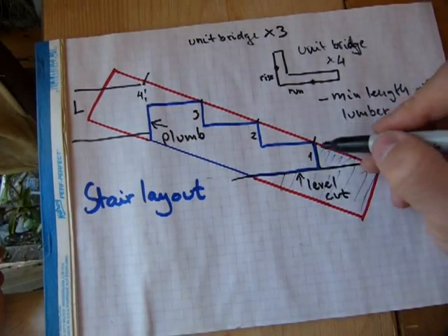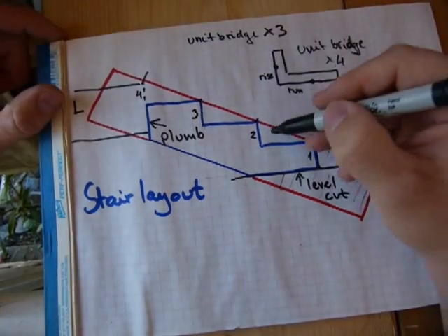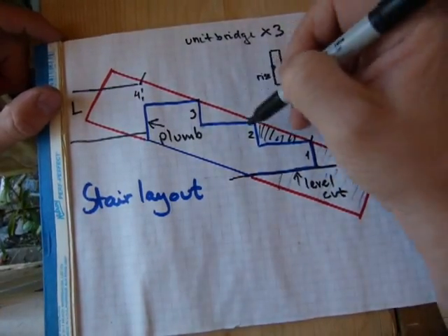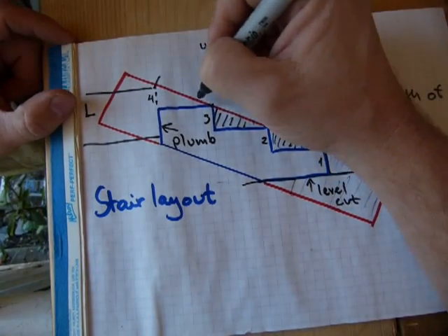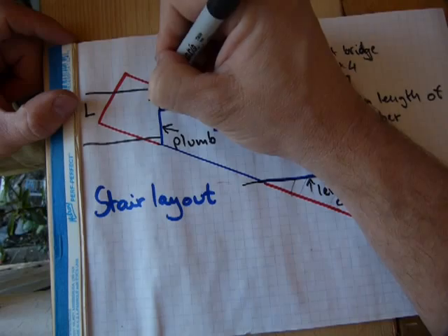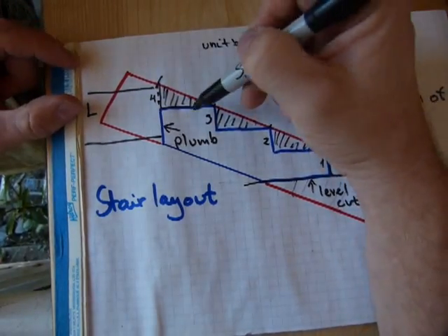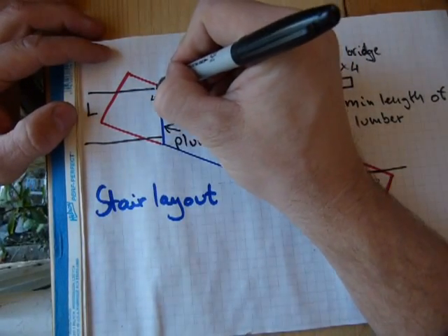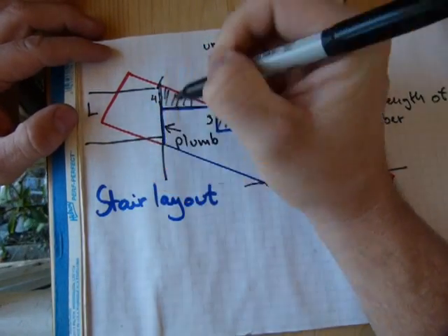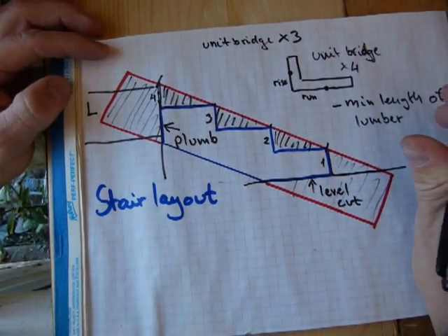So that will be cut away, but that's a line that we actually need. All this will come out, all this will come out. I'm going to place the framing square the fourth time here. All that will be cut away. I'm not going to extend the level line because I don't need it. I'm going to extend this line to make a plumb cut and cut away all that.